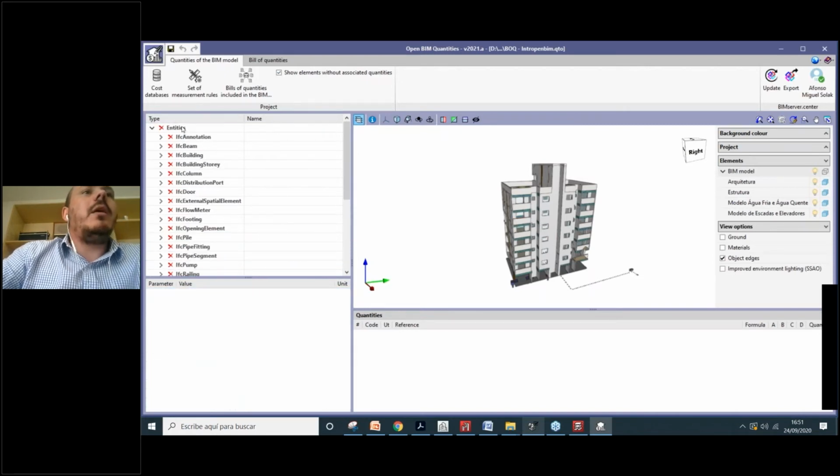menu here. Okay, so this project menu is organized adopting the classification proposed by the IFC format, the structure of the IFC format proposed by Building Smart. So inside of this format or this classification system, we have some entities. These entities are standard. So the IFC door is always called IFC door. The IFC column is always called IFC column.